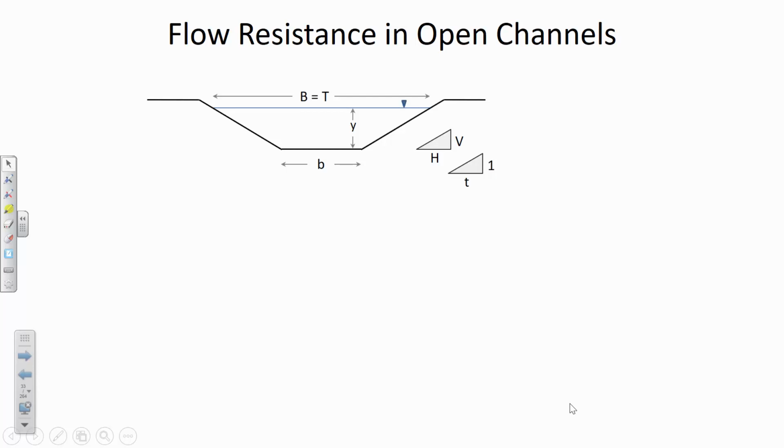In engineered channels, and in fact in natural channels, oftentimes we have this trapezoidal shape because although it's easier to calculate the flow conditions in a rectangular channel, a lot of the natural materials out there in the world can't support a rectangular channel like this. If you have water flowing through a rectangular channel, then the materials are going to just slope into the channel itself, and collapse in. There you could have a rock-lined channel, or if you had reinforced concrete, you could achieve a rectangular channel. But this trapezoidal shape is more common.